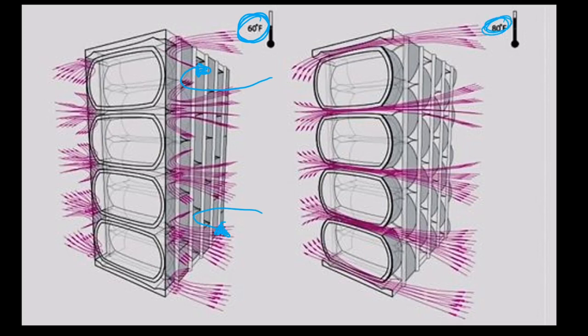However, now you can see it's reached 80 degrees and now they've started to open up. You can see that the system here, where they've curled open, as opposed to the other side, on the left hand side, where they're absolutely flat and straight. But you can see here that they're all opening up and creating those gaps, those vents right through to the other side. Look, you can see them just there, and you can see that the air is now traveling through, which is obviously cooling down in between the floors like that. So it's free ventilation is the way you want to look at it.